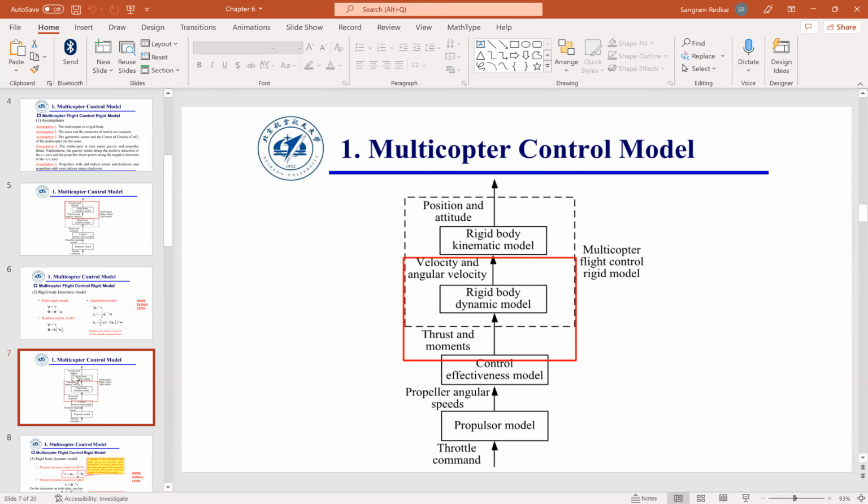Then what you do is you have forces and you have the external dynamics, you have the differential equation, and you want to make sure that the differential equation has negative real parts. Basically, the system is stable. So you have something called a control effectiveness model, and you have PID gains, or you add some sort of controller input that would stabilize that system.